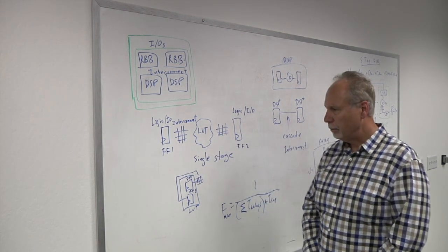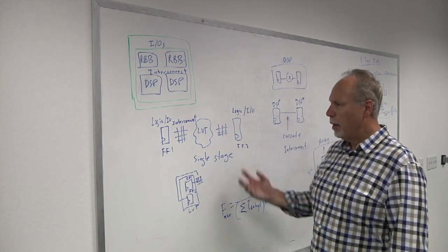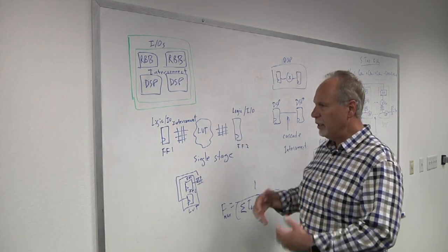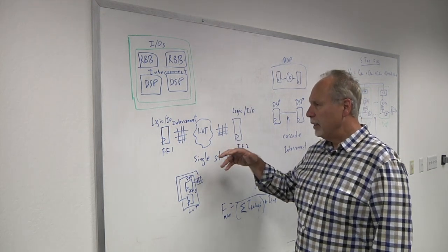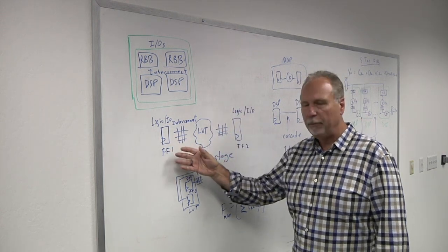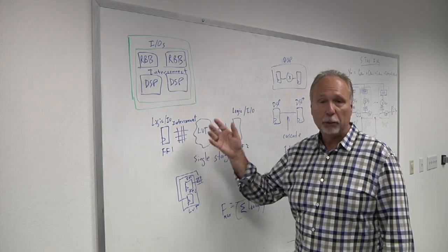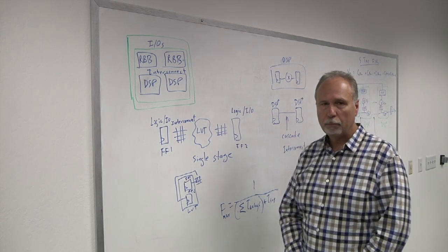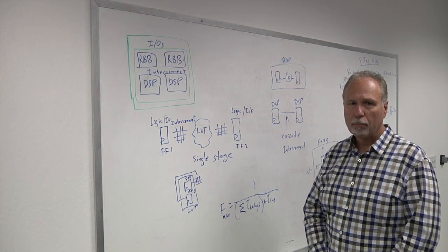And because this FPGA is embedded, you're actually working with the RTL code here, right? Yes, this is all part of the RTL, but the RTL is very generic. Once it's implemented in an embedded FPGA, it's actually synthesized and compiled into actual physical flip-flops and physical LUTs, and also uses interconnect fabric to connect all of those together. So the interconnect fabric is a piece of this because you're moving electrons around in there. Another piece of this is the throughput to memory, right?